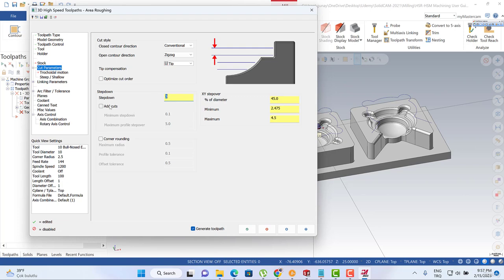If you intend to organize your step down process, you need to activate that parameter. For example, I can write here my step down can be reduced to 0.3 millimeter according to my step over. If my step over is 1 millimeter, then my step down is automatically reduced to 0.3 millimeter. And this is also my step over.